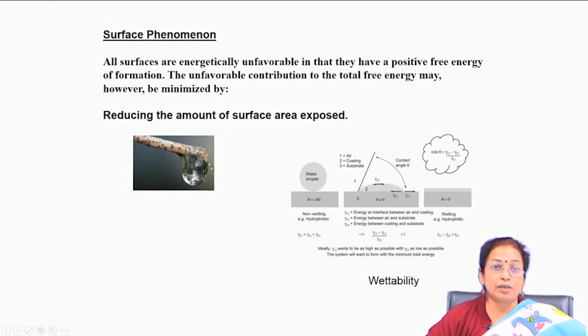When you pour molten metal, it pours in a droplet-like fashion. Similarly, when you synthesize powder by water atomization or gas atomization, its shape is always spherical, because a spherical shape has very low surface energy for its surface area. So droplet size is one important phenomenon related to surface energy.